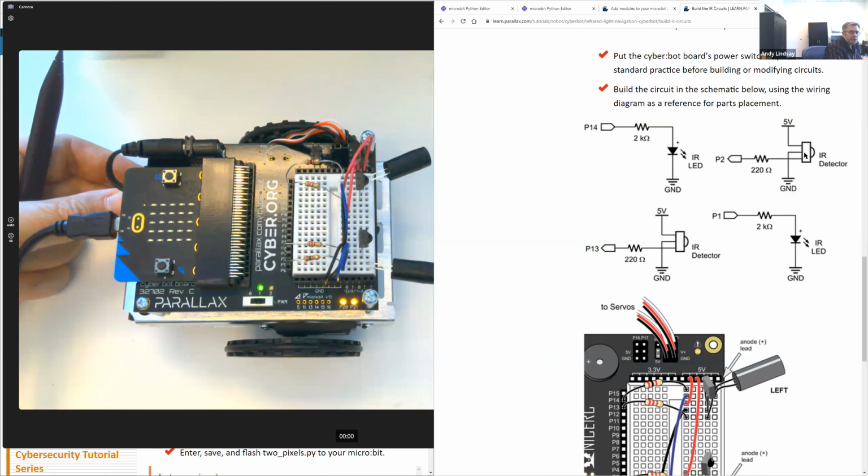And it turns out that there's a large resistor inside this IR receiver, so it's not technically necessary. You could have used a wire in place of this 220 ohm resistor, but wherever possible we try to use a 220 ohm resistor just to make sure that there's protection, because whiskers and push buttons are things that could potentially damage an IO pin if there isn't a resistor in the way when certain mistakes are made.